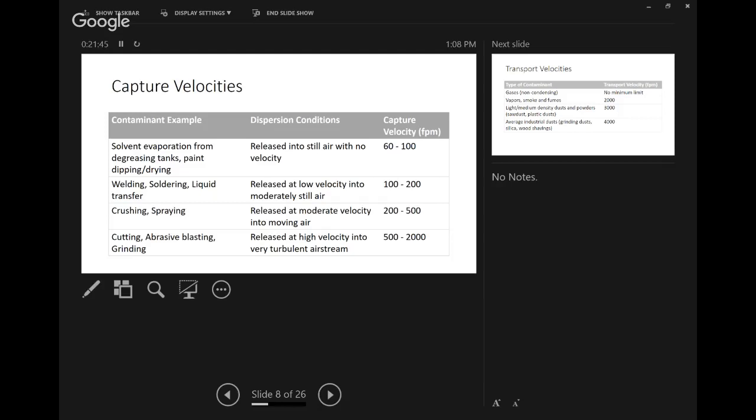Abrasive blasting, is anyone who could describe abrasive blasting to us? Okay, sandblasting. So for someone who doesn't know what it is, you're taking an item, let's say a painted panel, and you're removing the paint to get down to the metal. You're using an abrasive, anything from a silicon carbide to just pure silica to silica mixed with something else.